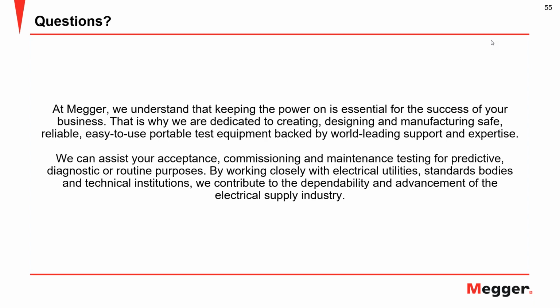And that's why the best practice is not to even attempt to do a tan delta measurement and interpret it as a bad cable, as unfortunately some people do. Don't do the measurement, and wait with this test, maybe at least, like Robert was saying, a year into service, under load. Eventually these byproducts will burn off, and then you get a true indication of the dielectric losses in that insulation.